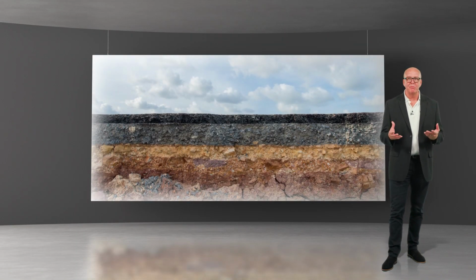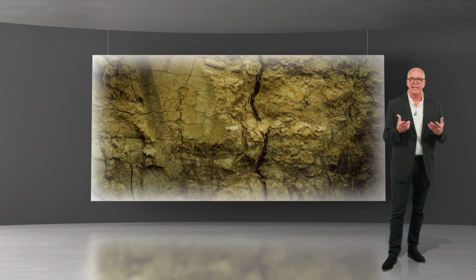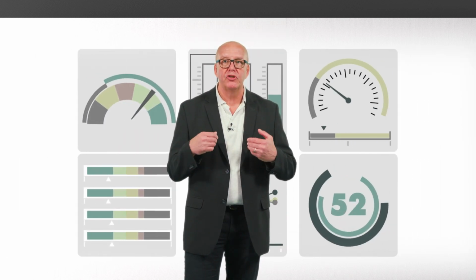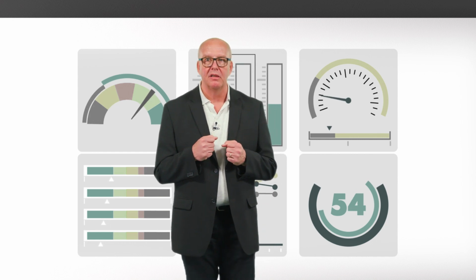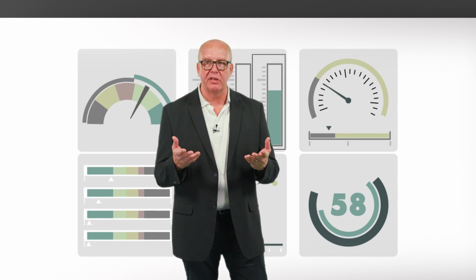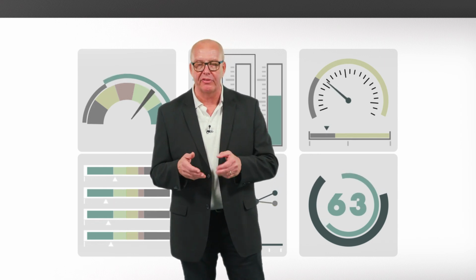Bottom liners can be made of different materials. As mentioned before, they can be mineral liners like compacted clay liners. Other options are synthetic materials like geomembranes made of polyethylene, geosynthetic clay liners or asphalt. As you have seen, there are a lot of parameters which are important in landfill design. The types of waste, lifespan, volume, waste density and height, as well as systems to remove leachate and gas.